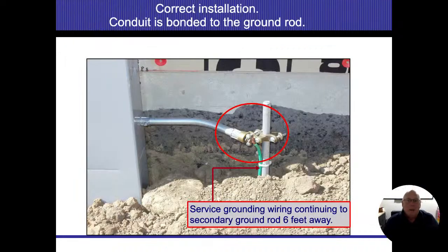All right. On ground rods, if we do use ground rods, and it is acceptable, and there's some areas that only want that. If you have a single ground rod that's being used, then there needs to be an ohm test. It has to allow for a certain amount of resistance, and it's a little bit of a process, costs a few bucks. It has to be done in the presence of the inspector, at least I think it does. Bottom line is nobody likes to do that. It's simpler and easier just to purchase 2 ground rods instead of 1. As long as you have 2 ground rods in the earth, then you do not have to do an ohm test. But the same rules apply, all right?